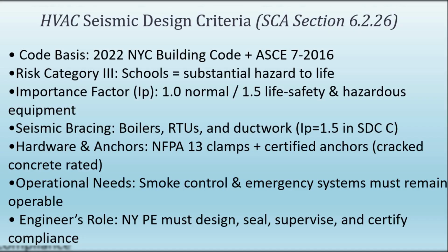Seismic safety is an important part of HVAC design in New York City schools. The School Construction Authority requires systems to be properly braced and certified to reduce risks during an earthquake. This section is based on the 2022 NYC Building Code and ASCE 7/2016, and applies to all new schools, major additions, and retrofits. Schools are classified as Risk Category 3, meaning they are considered substantial hazard to life buildings.